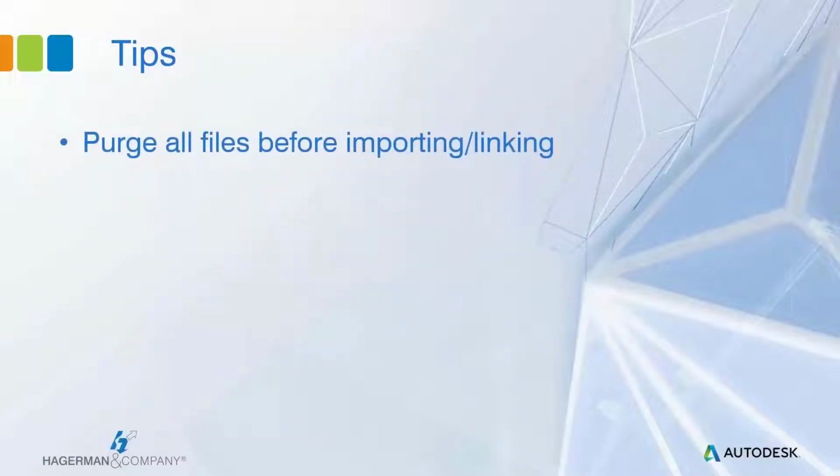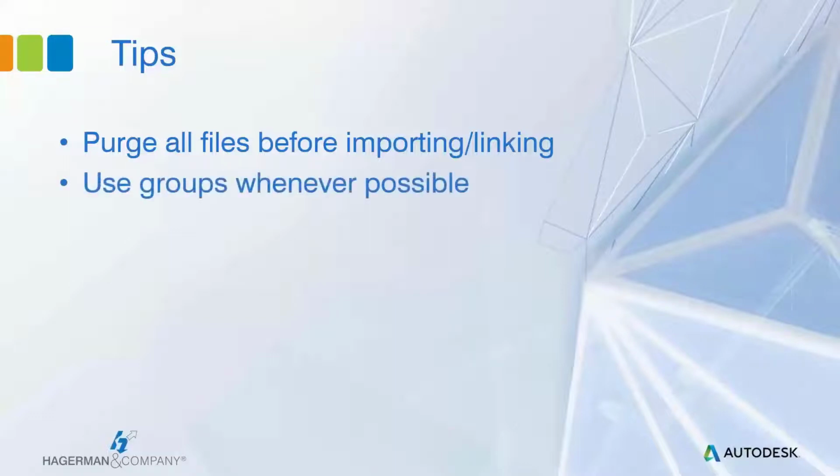Now for some tips. First, when you're dealing with larger files, no matter where they're coming from, be sure to purge those as much as possible before bringing them into Max. This will minimize the import times. Next, use groups whenever you can. Although Max creates groups for imported and linked files, you can still create your own or rearrange those however you need to help you keep things organized.